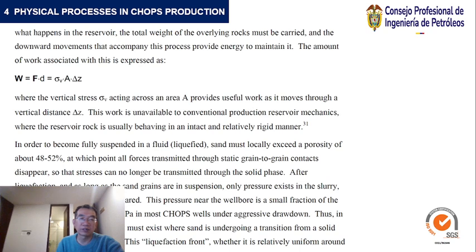After liquefaction, and as long as the sand grains are in suspension, only pressure exists in the slurry, and all mixture stress has disappeared.